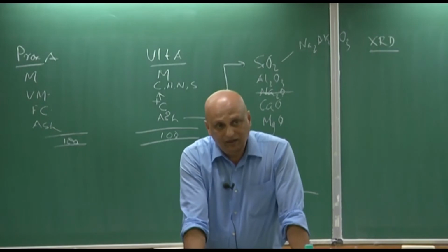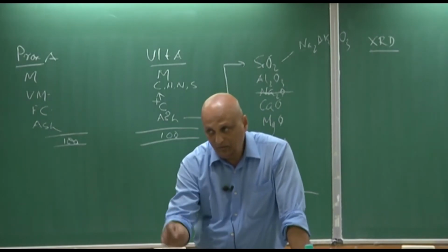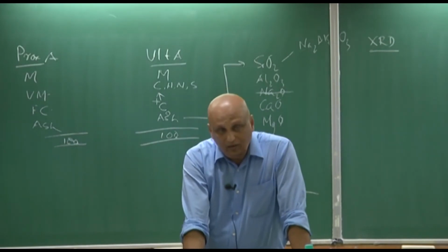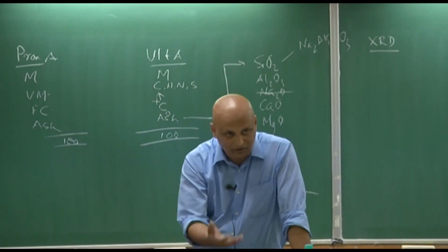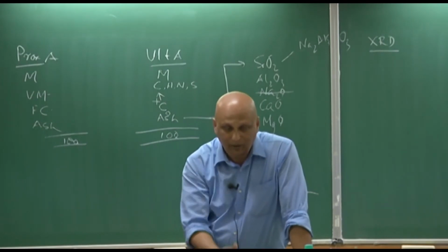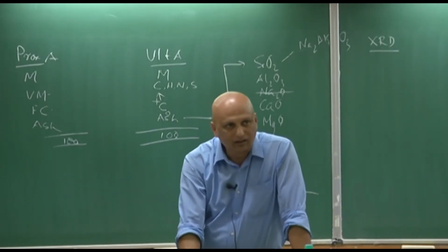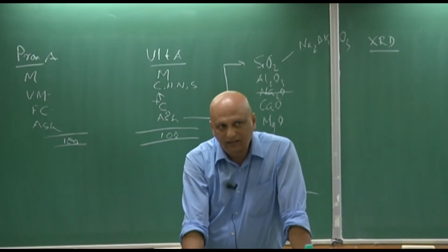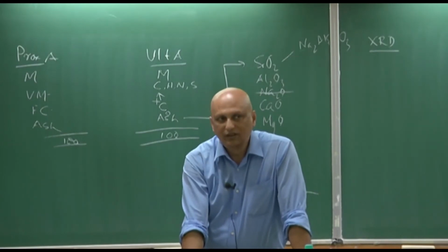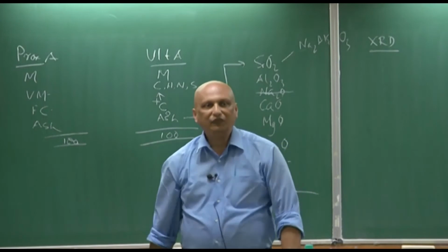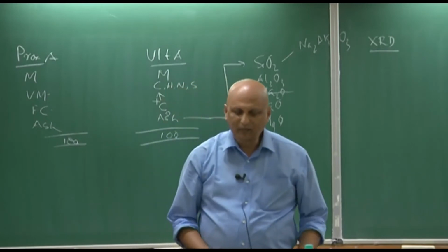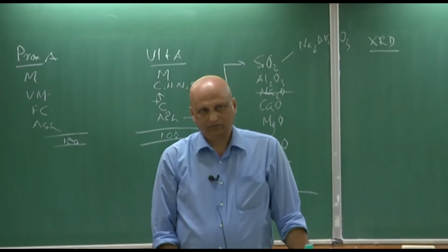The important thing is you have to put only the designated amount, because if you put more than the designated amount, then too many volatiles will be released, as you would expect. More coal inside means more volatiles, therefore more pressure rise. So the cover will go off. As soon as the cover goes off, the volatiles come out, they get combusted, and they then also burn the carbon. So you will get an artificially inflated value of volatile matter. So volatile matter measurement is quite tricky, unless you know it.